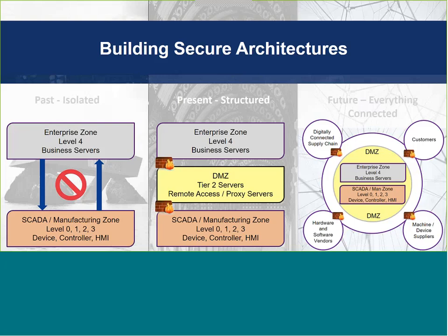and especially if you were to use a layer 3 device where those firewalls sit, it would allow you to implement zones and conduits. If we take that reporting server scenario again, you could introduce a conduit whereby you allow traffic from the DMZ to the SCADA and manufacturing zone, but only allow HTTPS traffic. That means you're able to communicate with that reporting server, but nothing else. So it's a much more secure way than an air-gapped system, because you've got the flexibility to communicate with multiple layers.